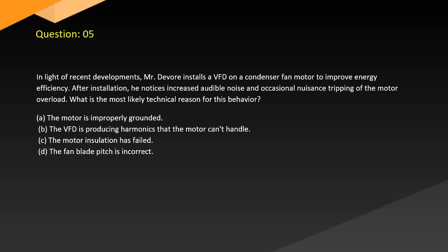Question 5. In light of recent developments, Mr. DeVore installs a VFD-driven condenser fan motor to improve energy efficiency. After installation, he notices increased audible noise and occasional nuisance tripping of the motor overload. What is the most likely technical reason for this behavior? A. The motor is improperly grounded. B. The VFD is producing harmonics that the motor can't handle. C. The motor insulation has failed. D. The fan blade pitch is incorrect.